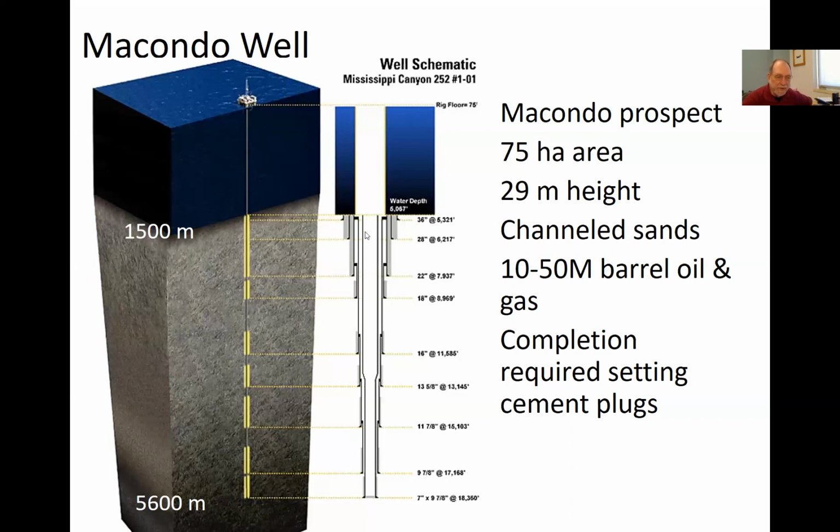As they get deeper and deeper, they put in casing around this. So they start out at the seabed with a casing which is about 36 inches in diameter. Okay? And this goes down and down. By the time they get into the reservoir, they've gotten down to a pipe size of about 7 to 9, 10 inches in diameter. So a very narrow little pipe is required there.